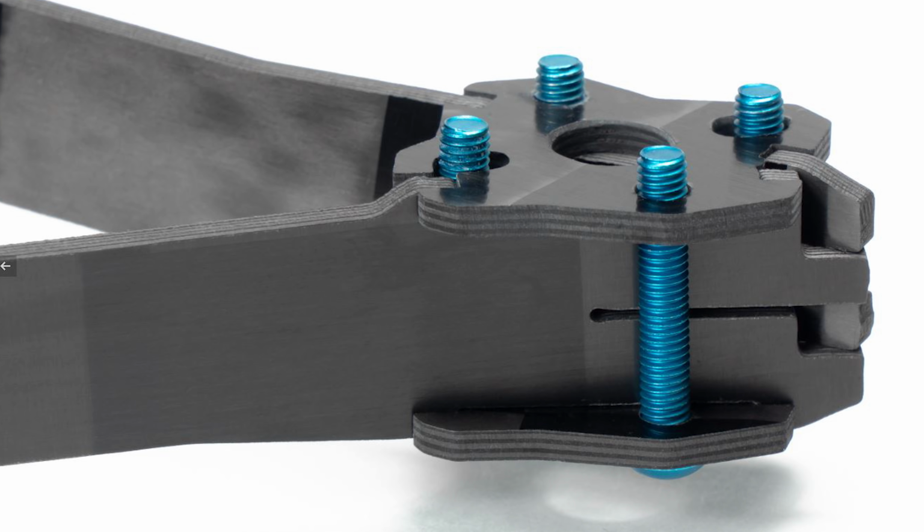Your drill bit is a circle, and that circle has a radius to it. So usually it's 2 millimeters radius. They use 2 millimeter burrs to cut these sheets because it's the most efficient size and gives you enough resolution of your radius of your turns so that you can get done what you want to get done. Now, I cut a lot of my stuff with 1.5 millimeter radius, which does cost a little bit more and does wear out faster, so that I can get not just a better fit, but also better tolerances on my holes and shapes.